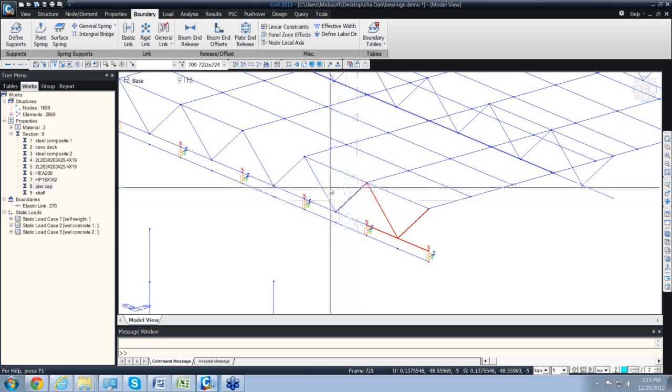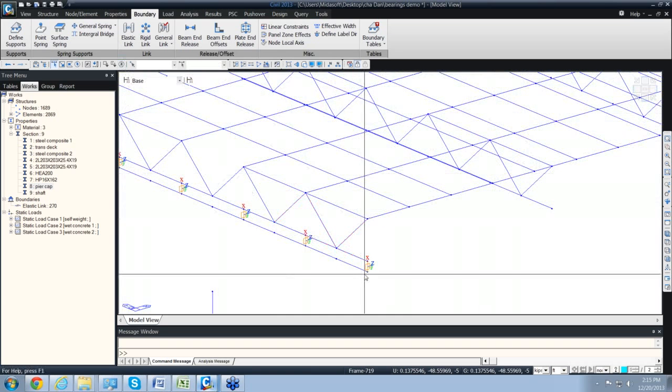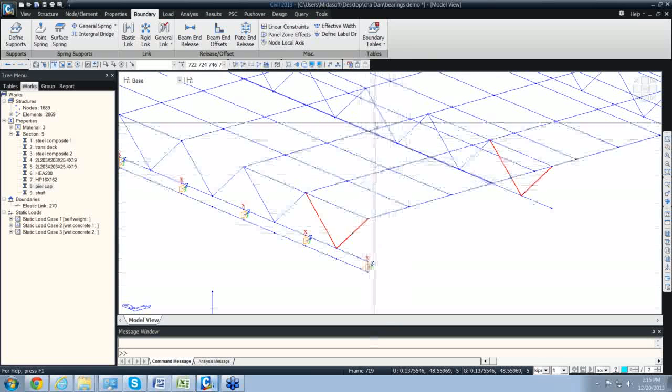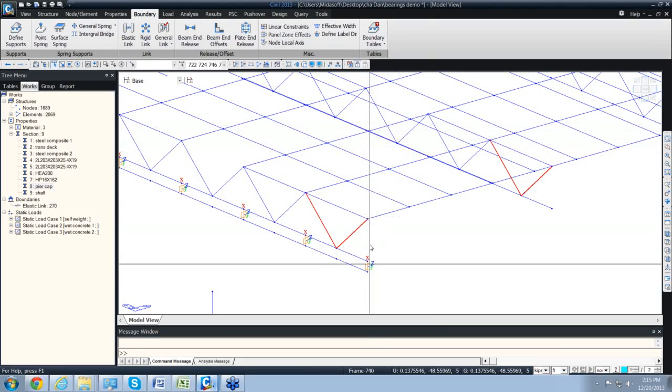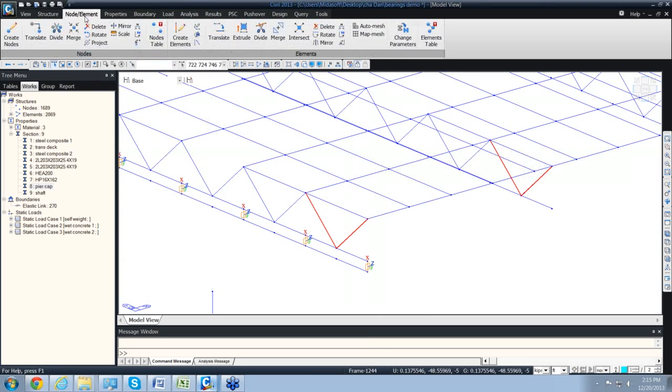Along the length of the girder, in the longitudinal direction. Okay, so between this cross frame and this cross frame. Oh, you have a lateral here. Okay, perfect. So if you have it there, then you can model the actual element for that. You don't have to create a link for that. You can model the actual element if you have one. The bottom. So I mean, just draw it.